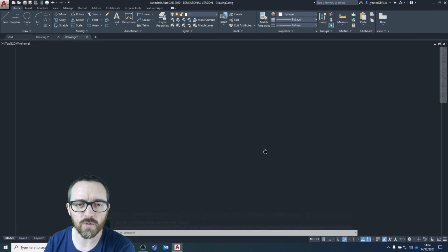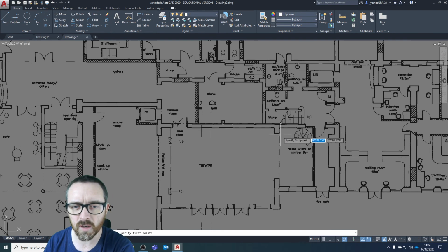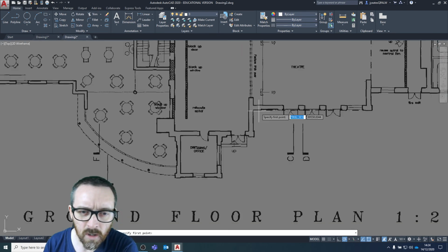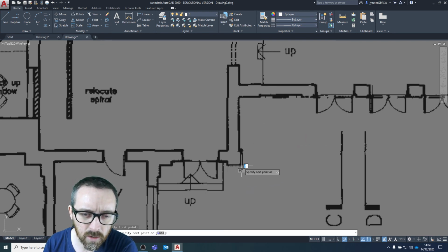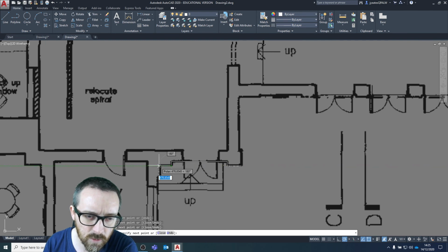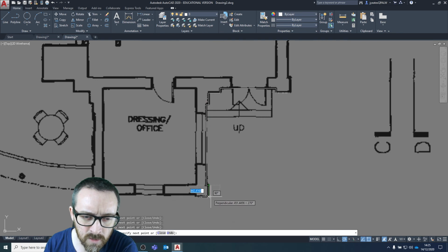we're going to start to draw the plan of the theatre, and we're going to do that with the line tool. Okay, so I'm going to click just around this shape, just by going to the corner here, and my snaps are turned on, so it's snapping into place, and I can just draw around the edge very accurately as I go. Okay, so I'm going to click here. I can also go back and highlight points to ensure that they're parallel, which is really good too.